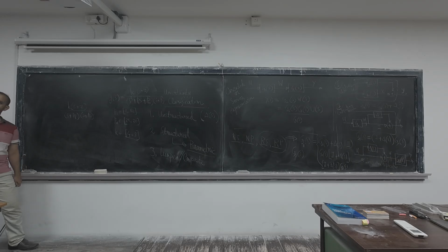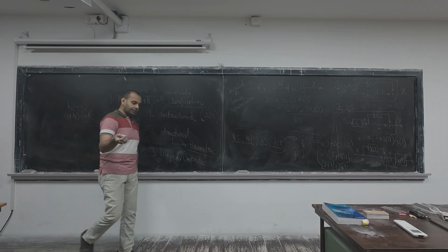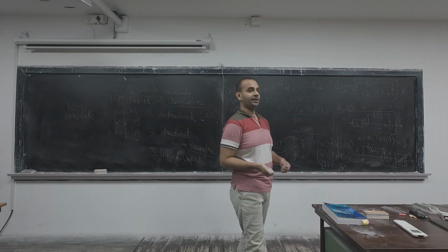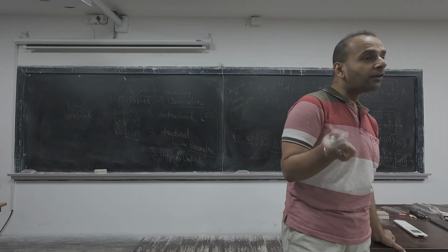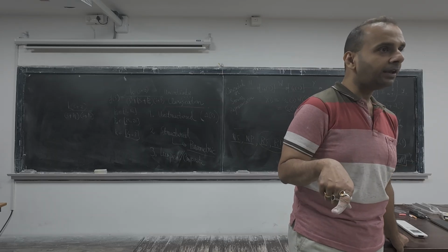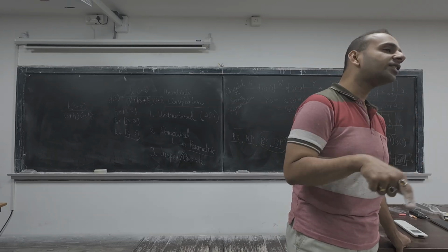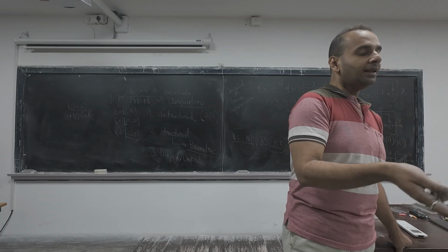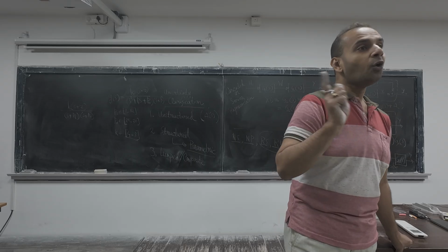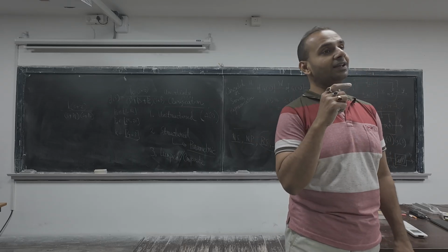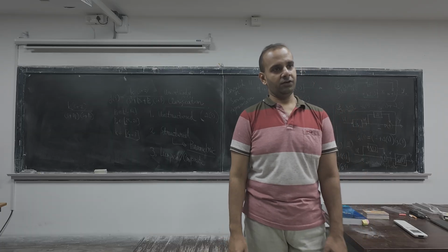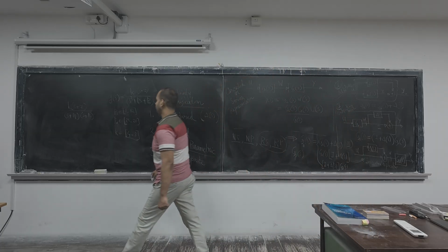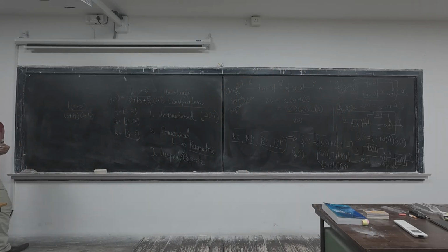No, pole zero cancellation, how is it related to the plant being unstable? What is the reason behind the pole zero cancellation? That is a lack of controllability or observability, right? So that is the problem in the structural property. We will discuss it, of course, but what you said, that this pole zero cancellation is not because of that. Originally it is a problem with its structure. But what you said is also an important point.